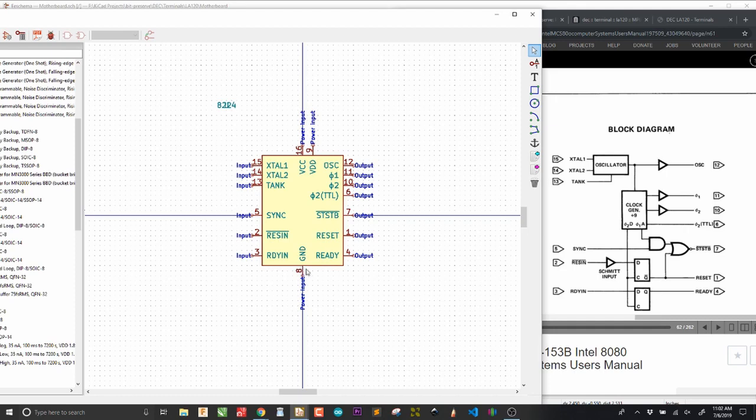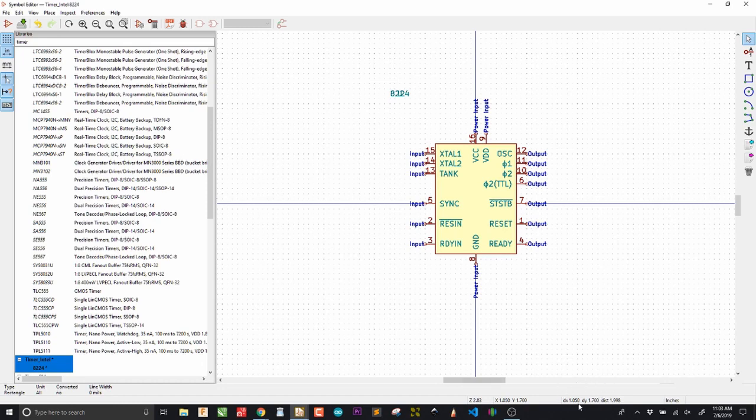the pin. Now, the final thing that I want to do is I want to check to make sure that these pins ended up on the 100 mil grid. If you look down here, you can see the position of your cursor. So I'm just going to position my cursor on this pin, and I see that it is 0.6. Position it up here, 0.7, good. Position it here, 0.5 and 0.4, good. And negative 0.5 and 0.4, that's also good. So if I saw a 0.05 somewhere, then that means that I would have to move these pins over by 1. And that's it.